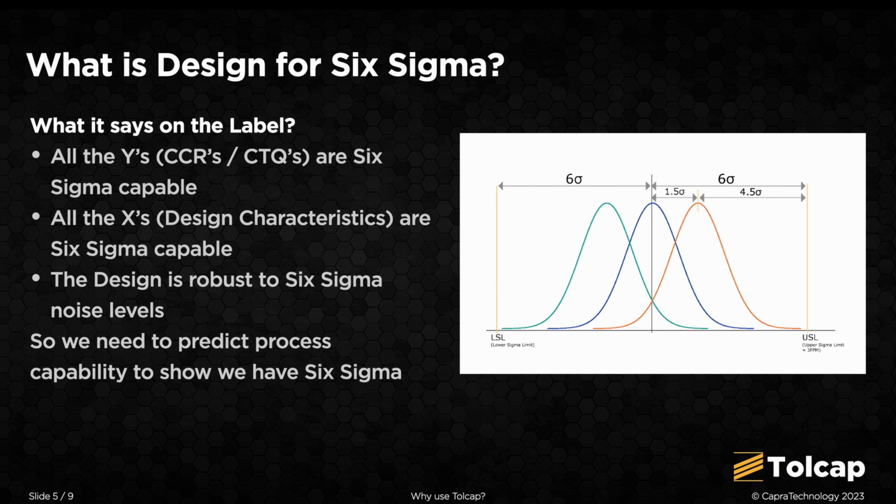A batch of prototype new transistors would be characterized, that is, the parameters of interest measured for all the samples, so a datasheet specifying the device performance could be issued. Setting the datasheet limits plus and minus 6 sigma from the measured sample mean would allow 1.5 sigma either way for the mean to vary. There's that probably confusing process shift that came up if you had Six Sigma training. And the remaining 4.5 sigma gives a projected CPK of 1.5.